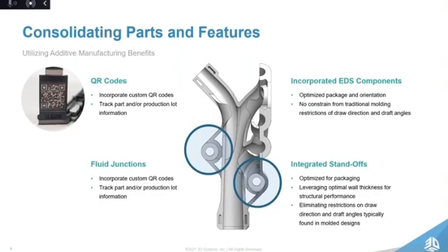So again, moving away from those constraints of injection molding, the part can be totally optimized for its intended use, with precise conformal fit within any space on a vehicle, and with any kind of accessibility. That's kind of pertaining back to the serviceability point that I made earlier. The space that the part occupies and the space around it can form part of the design, to ensure that the areas otherwise thought of as inaccessible or too complex to fit a part into can be used. By incorporating the fitting guides into a part, assembly also becomes much easier and without error.